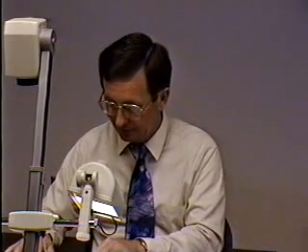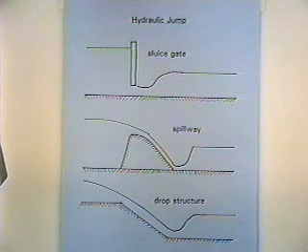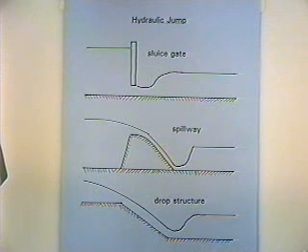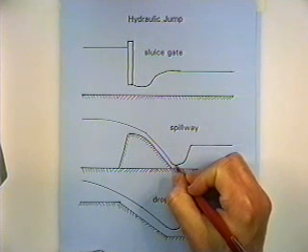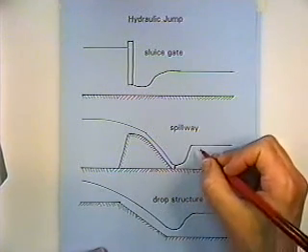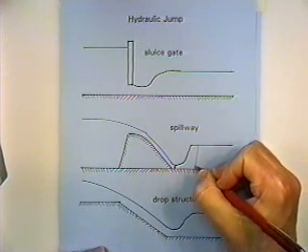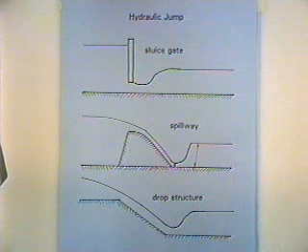If we take just a moment here and go back to this page of the notes, let's say we do a couple of things. We can use any of the hydraulic jumps we want. Let's go ahead, we just did some work with the spillway. Let's say that we do the computations we just did. We computed that depth, and having computed that depth, we use conservation of momentum to compute this depth. And it came out like so.